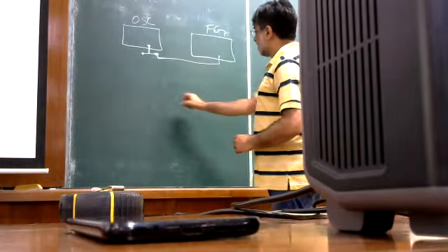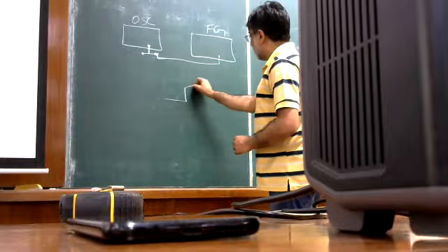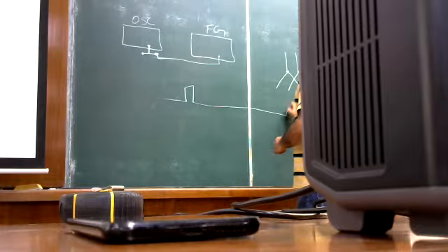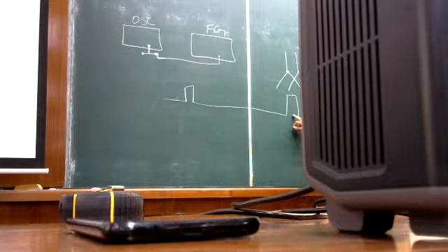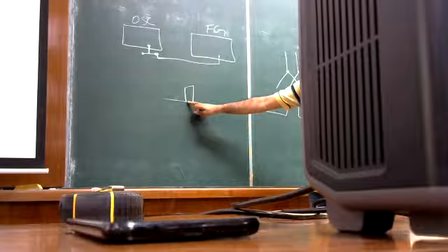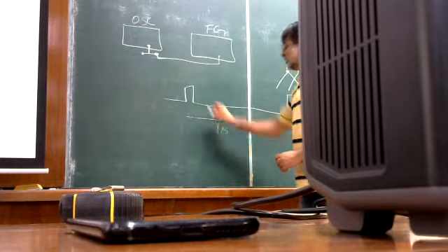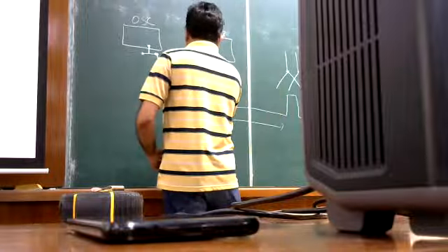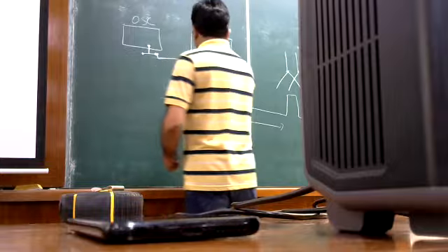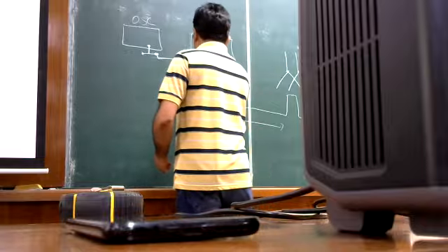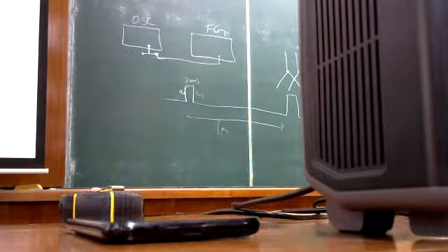From the function generator, I'm going to create a pulse which repeats at some slow rate. Right now, I think it's set to about 1 megahertz repetition rate. So from here to here, this is going to be like 1 microsecond. The pulse width itself is about 20 nanoseconds, and it has a rise time and a fall time of 9 nanoseconds. That's just the instrument's capability to generate sharp pulses.